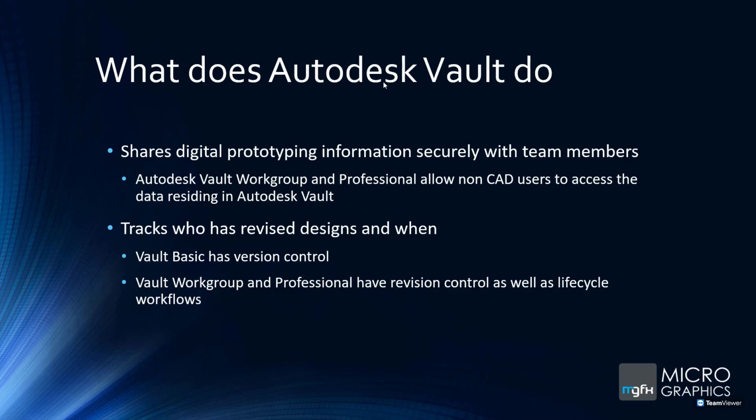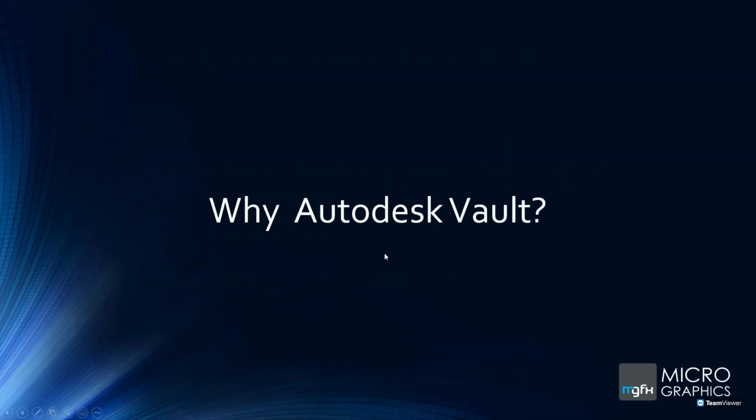Okay, so if it's sitting in release and you have to make a change, an engineering change order gets processed. What parts get put to that? You put all that digitally, so it's not something that you handwrite out; it's built internally into Vault Professional. Then it goes back to work in progress, so it can automatically bump up to maybe revision B or revision C, or maybe a secondary bump or tertiary bump. Okay, so that's a little bit of what Autodesk Vault does.